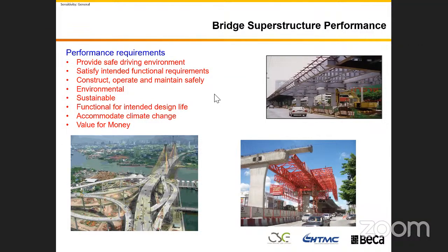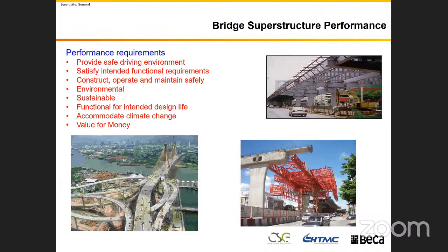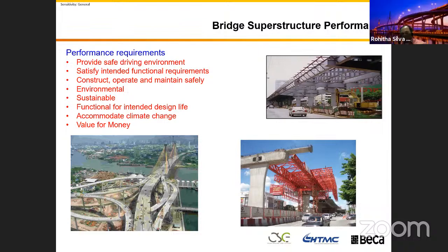Mr. Tanis wants to know how pedestrian bridges vary from typical bridges from the loading perspective, especially resonance and damping due to human locomotion. That's a really good question, because pedestrian bridges are slender and longer, and people are walking, so they vibrate.